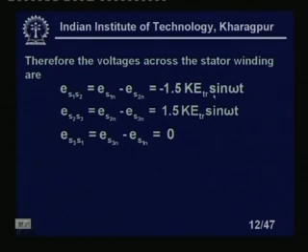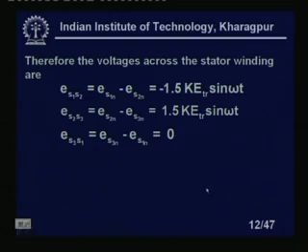So, it will give the position of the synchro rotor. The transmitter rotor position can be predicted from these voltages, because in all synchros we get three different stator voltages, and they indicate the position of the rotor.